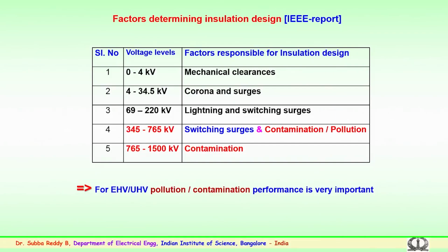So, how serious is that, how does it happen, why is it so important? The reason is that the contamination or pollution flashover occurs at the normal working voltages.